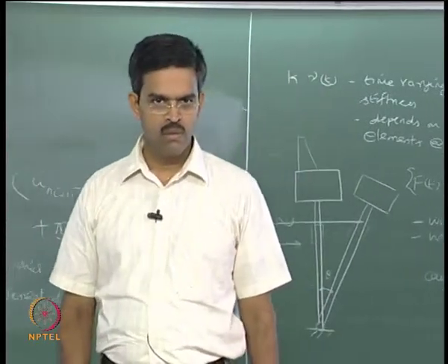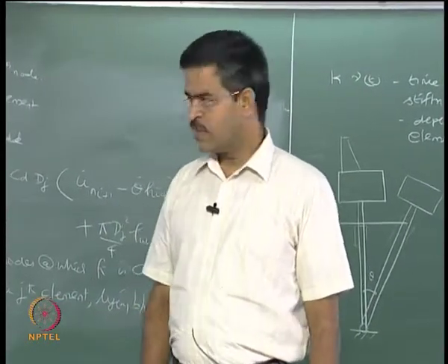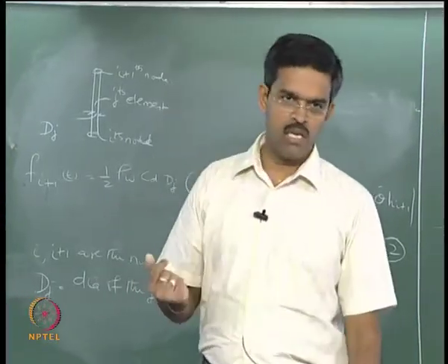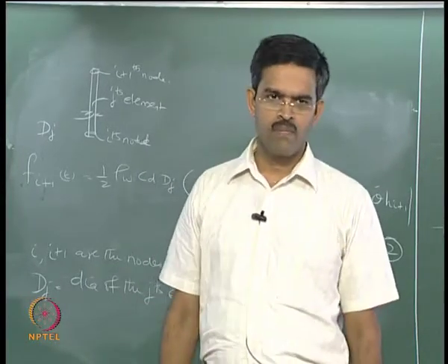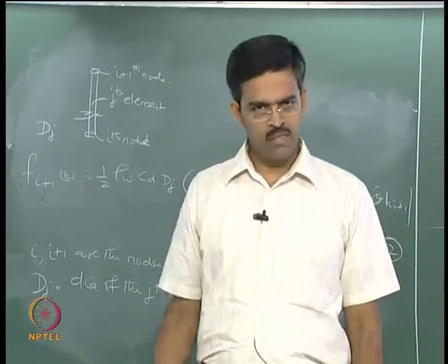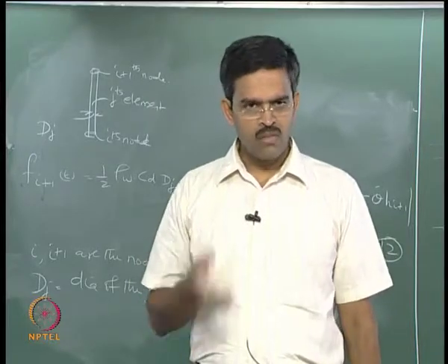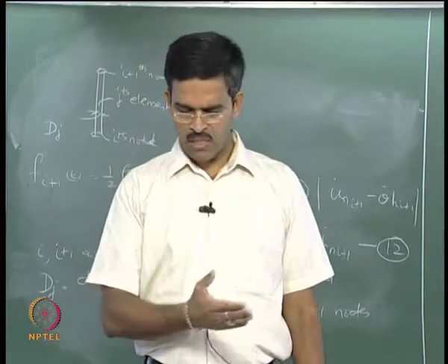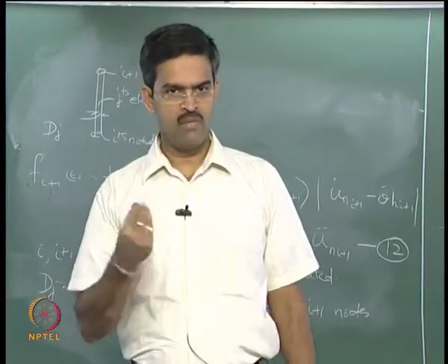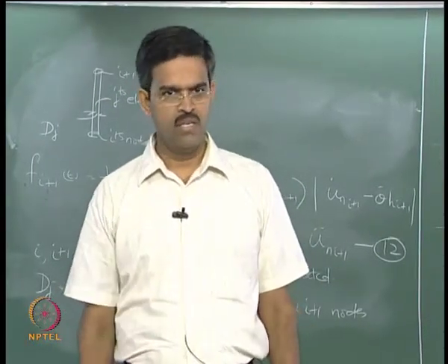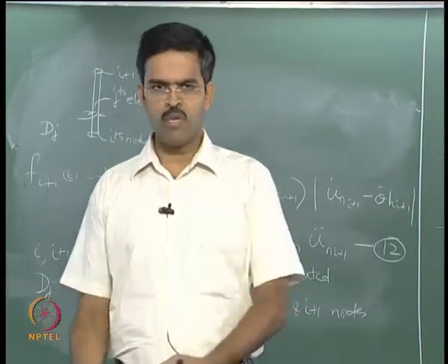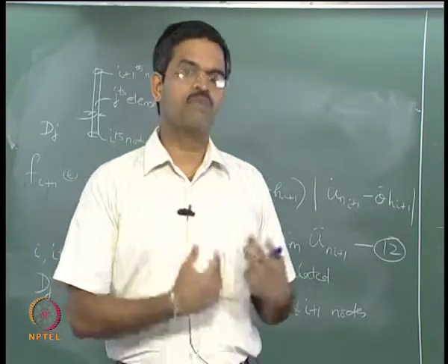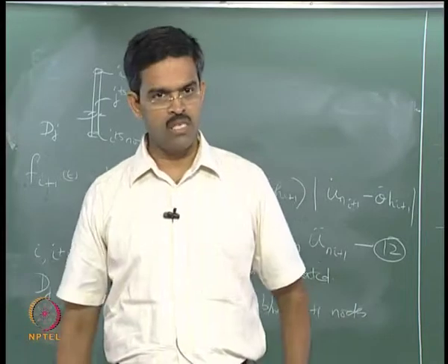Not as the outcome of the dynamic analysis. That is an interesting question. When we solve this equation of motion, the variable in the equation of motion I think we agree is theta, which is the displacement degree, in this case rotation. So either I must get the time history of theta of t, for any instant of time what will be the rotation of the base at the hinge I can find, or if you do a frequency domain analysis I will get power spectral density function for a wide range of frequency of theta.